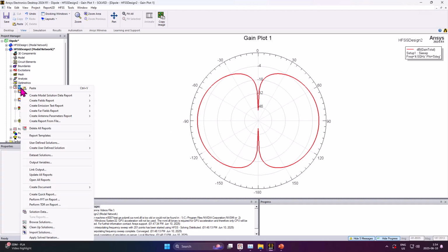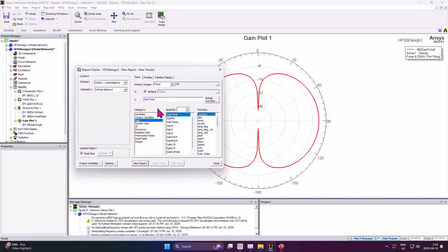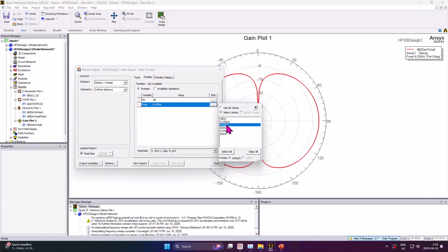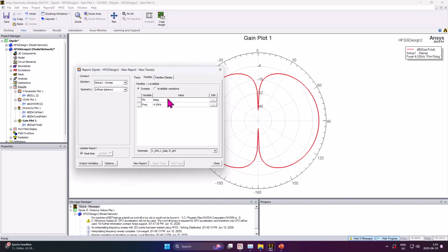And also you can go here to the far field and plot the rectangular plots. With these rectangular plots, again, you can plot the gain or the directivity, any of them, and you can select the dB. So I just wanted to show you the copolar and cross-polar in dB form, and I'm going to put it on 4.5, and for only one of the phi, which is 0.